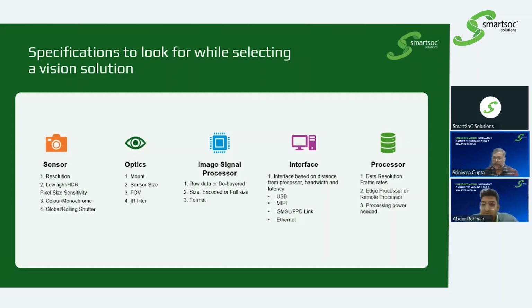Understood. But all other processing we can do for both the raw data as well as the color debayered data. That is the reason why, if we have stereo cameras, mostly stereo cameras are monochrome, because data is most important. You're getting the data and trying to calculate the depth. You don't need to represent it in image format, right? Right. Exactly. Understood.